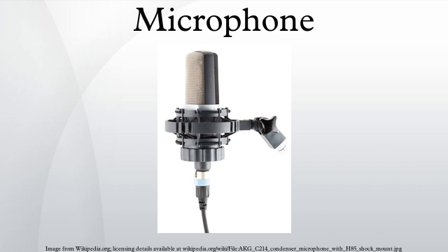Speakers as microphones. A loudspeaker, a transducer that turns an electrical signal into sound waves, is the functional opposite of a microphone. Since a conventional speaker is constructed much like a dynamic microphone, speakers can actually work in reverse as microphones. The result, though, is a microphone with poor quality, limited frequency response, and poor sensitivity. In practical use, speakers are sometimes used as microphones in applications where high quality and sensitivity are not needed, such as intercoms, walkie-talkies or video game voice chat peripherals, or when conventional microphones are in short supply.